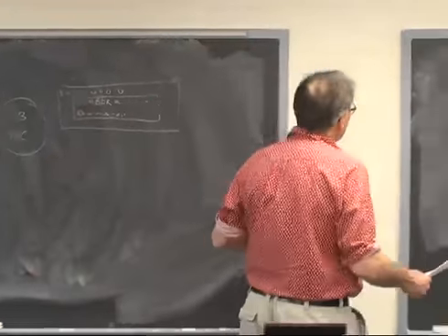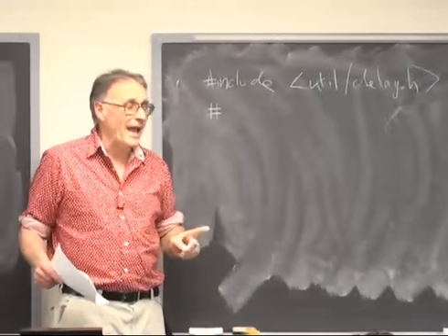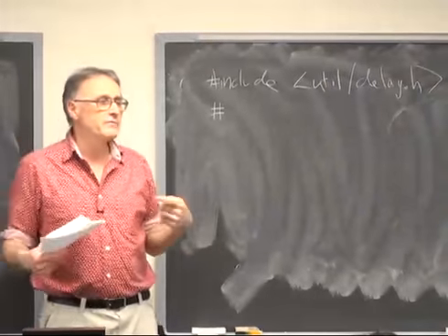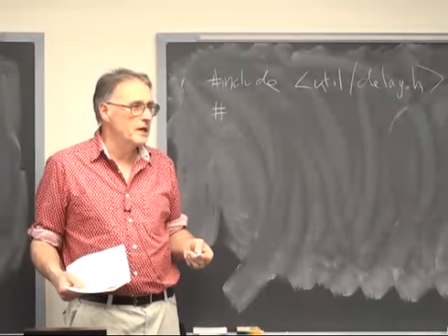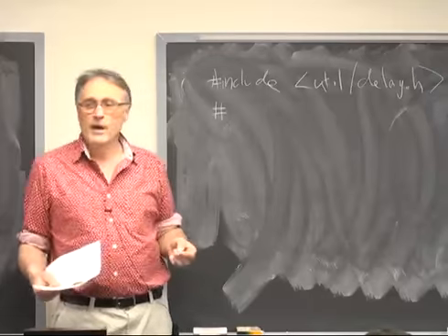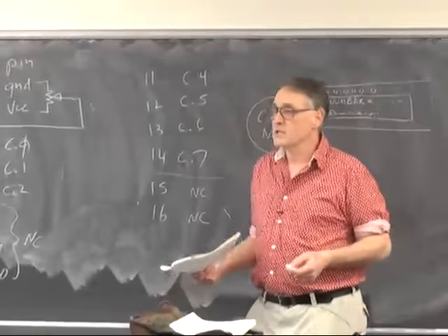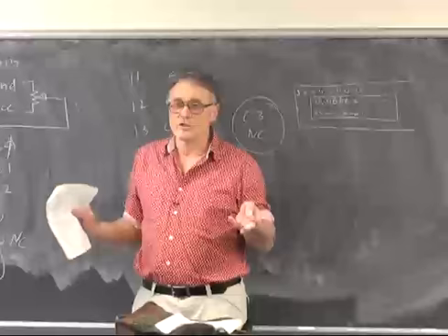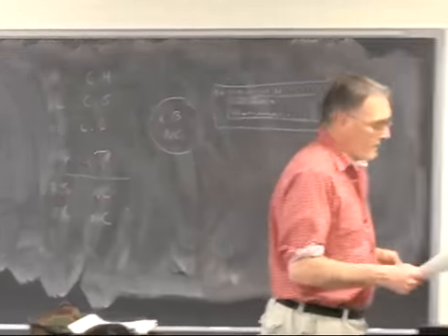The particular example we're going to use here also stores some strings in Flash. Now, Flash is a relatively large resource on this chip. There's about 64K of Flash. RAM is relatively small at around 4K. And so anytime you can put a large constant string in Flash, you're going to save useful RAM memory space.